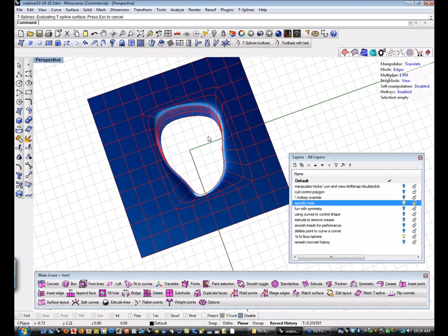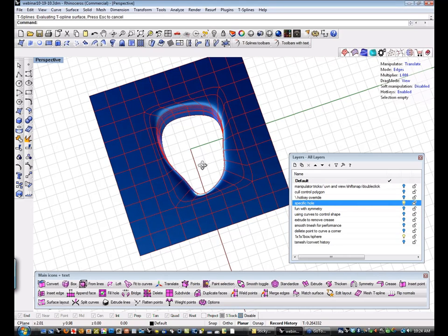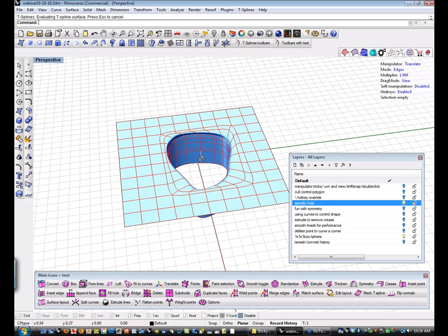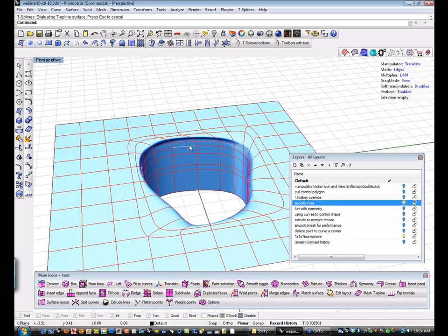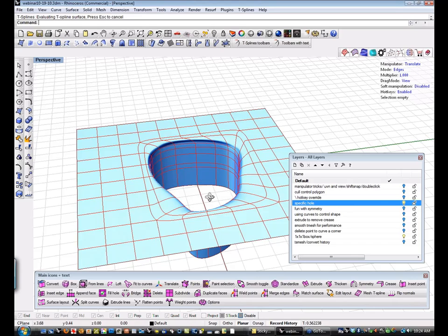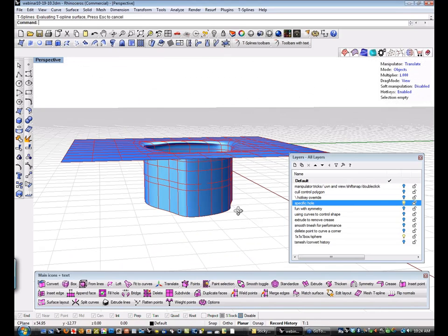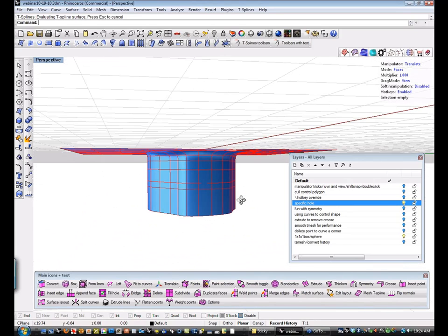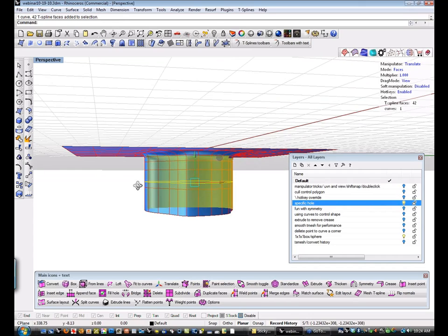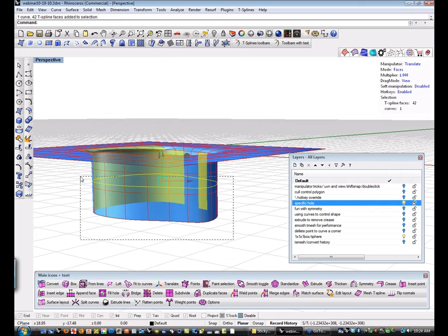So, for instance, if you watched the helicopter webinar and you saw how I did the rear tail rotor, that's exactly how I did it. I got the hole somewhat close. I used an extra piece of geometry stuck off the back. I bridged to it, and then I deleted that original piece of geometry. And I could do the same thing here if I were to go in and grab the faces here, get rid of all of this stuff.